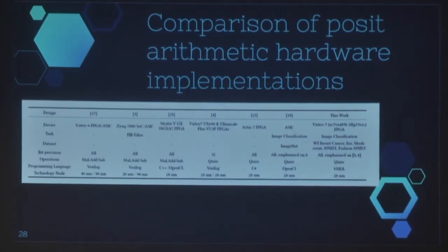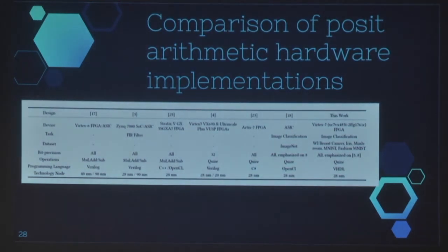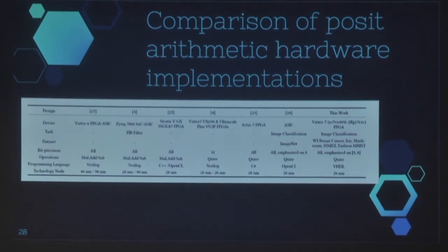There are few implementations of posits available. If you look at different Virtex-6 FPGA or Zynq implementations on different kinds of FPGA, some of them have just done multiply, add, or subtract, and some have done an FIR filter task. Our implementation of all this is on a Virtex-7 FPGA, and our implementation is in VHDL.